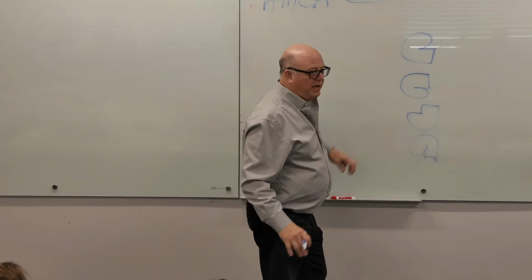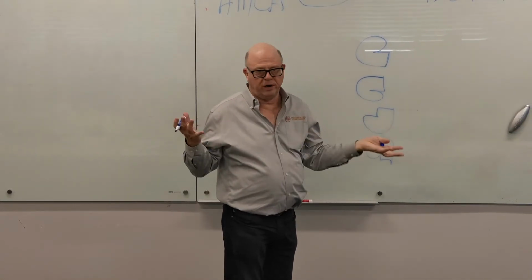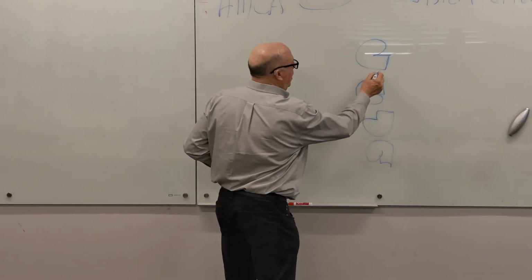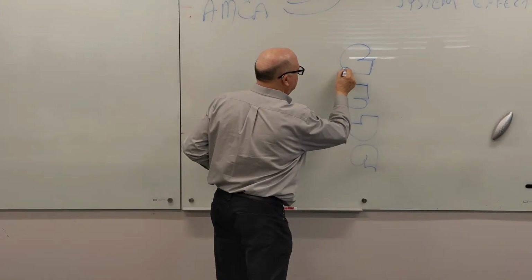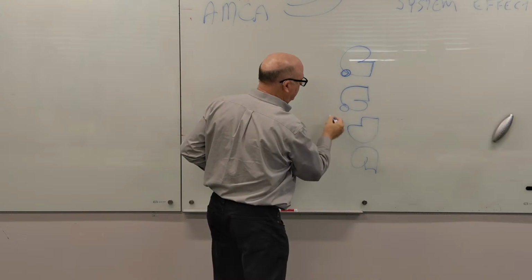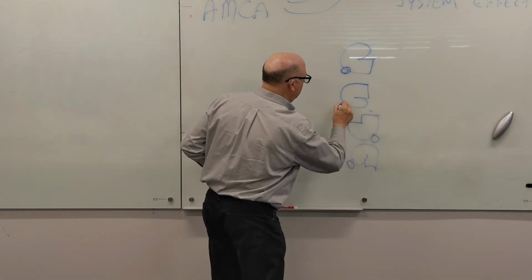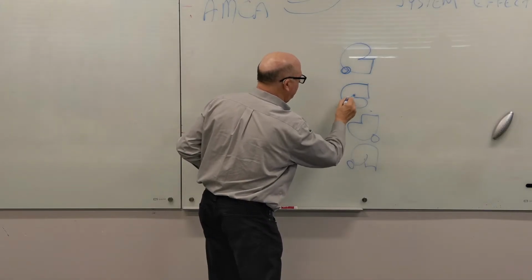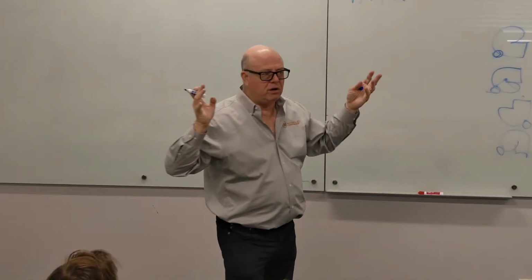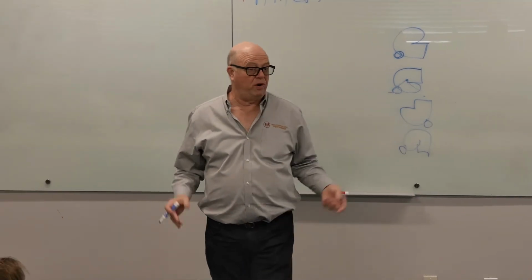If there is a motor and a belt drive thing, and some of them are ECM and direct drive now. The bigger it is, the more likely it is to have a belt drive. But where the motor gets mounted is usually on that back curve thing. So here it's there, but here it's here, and here it's here, and so the base, and you've got a fan shaft, right? So there'll be some kind of a support for each end of the shaft with the bearing and all that sort of thing, right? So where the motor goes varies with which one it is.